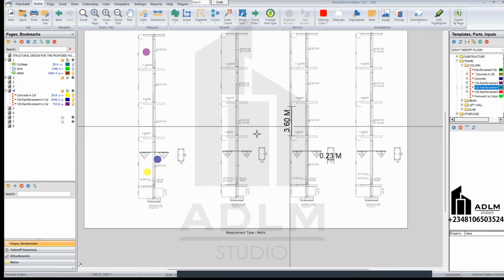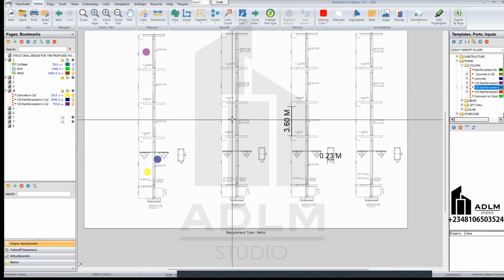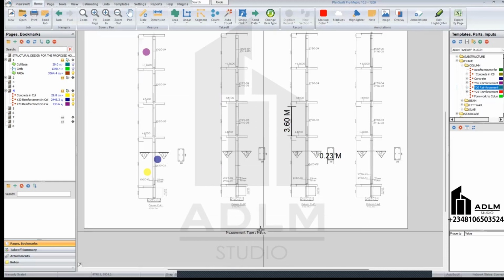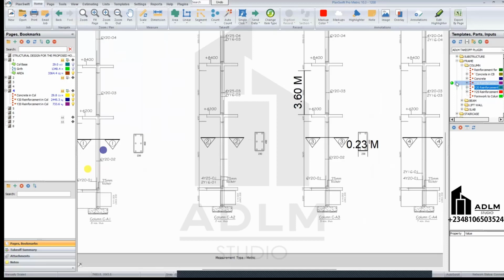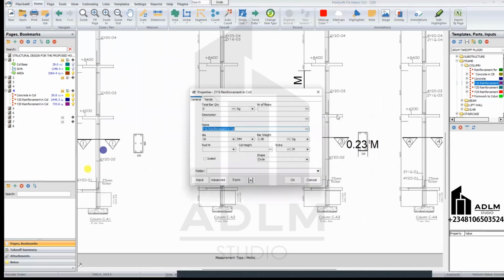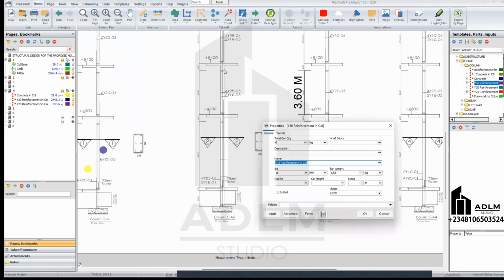So what I'll do is first I'll pick my 16 at once. So we have the 2 of this and we have 7 of this, which makes it 9 in total, right? So for my Y16, I'll come back to Y16 over here. Turn this on for Y16. Numbers of floors, I remember it's still my 3 floors, but this is now 7 plus 2, that's 9 times 3, right? The numbers of bars should be 2 this time around. Specify 2.